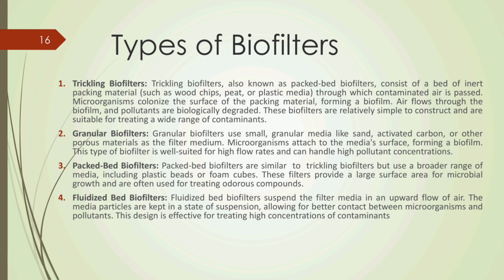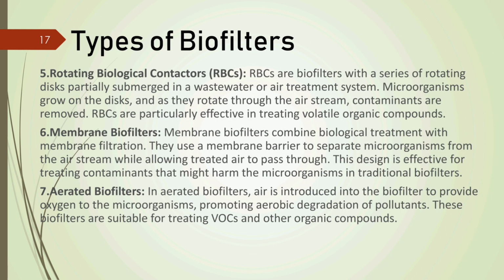Fourth is fluidized bed biofilters. Fluidized bed biofilters suspend the filter media in an upward flow of air. The media particles are kept in a state of suspension, allowing for better contact between microorganisms and pollutants. This design is effective for treating high concentrations of contaminants. Fifth is rotating biological contactor (RBC).